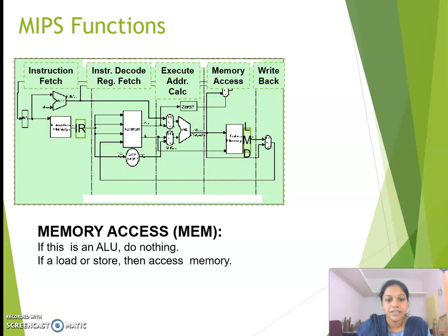Okay. The next step is memory access, where load and ALU has nothing to do with this memory access, like add, subtract and so on. If we want to load and store some values into the memory, then we need this step. So we go to the data memory. In case we want to load the data from the memory, we bring in the data. In case we want to store the data, we do it here. Okay, so load and store operation, we need to access the memory, and that is taking place here in this step.